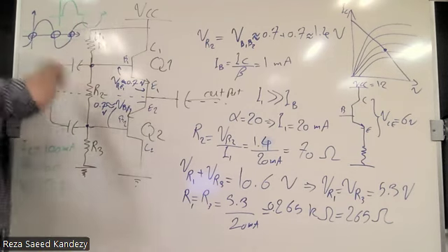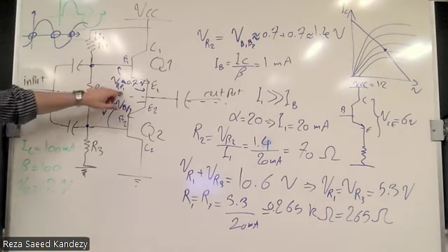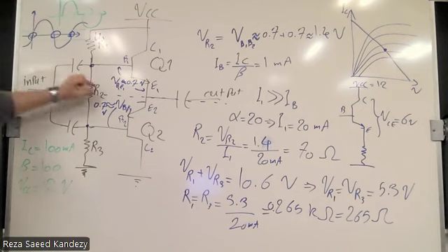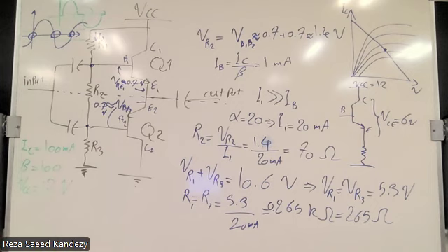And again we have zero and repeating. So we have a distortion when the signal crosses zero. The reason is that the base-emitter voltage between the two threshold lines is lower than what we need, so both switches are off.